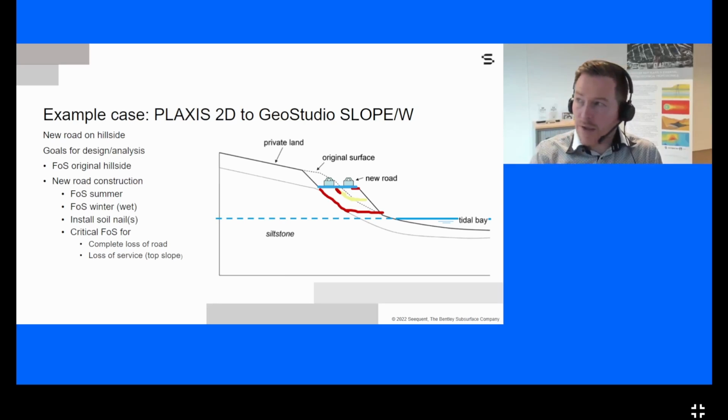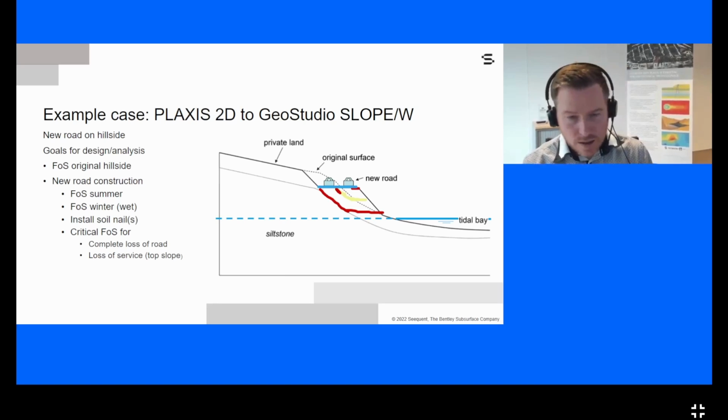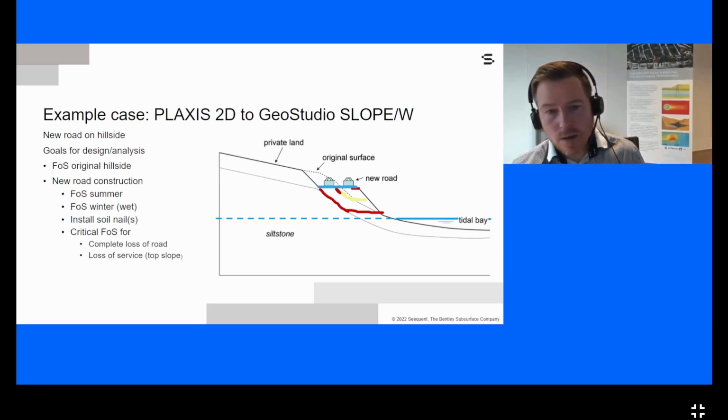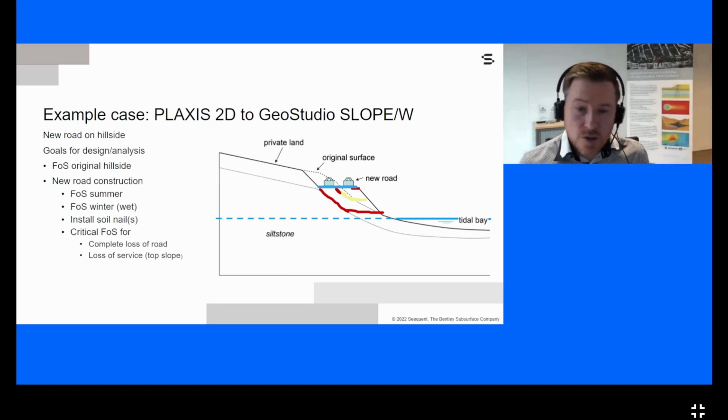What you can do, and that's also shown by Chris Callan in the demonstration, is clone an existing model, and then inside Geostudio you can change the slip surface direction. Maybe you also want to change the limit equilibrium method. So you can just click on the define project item, and then you can set the direction of the slip surface directly in Geostudio.